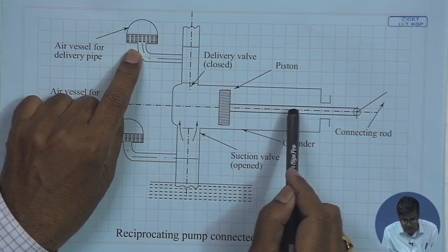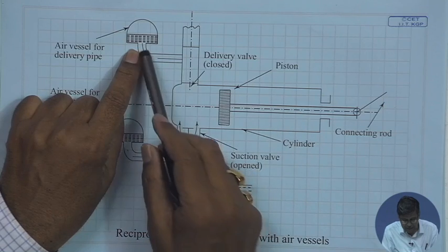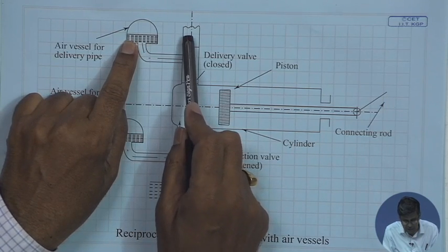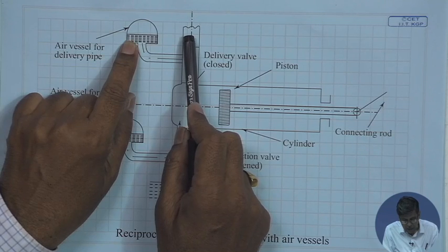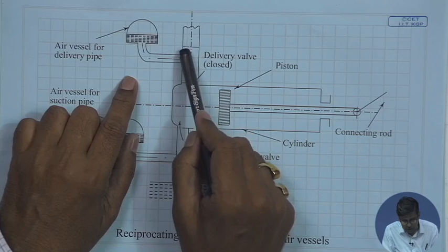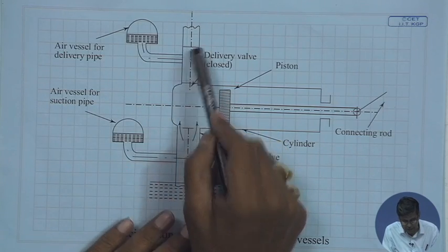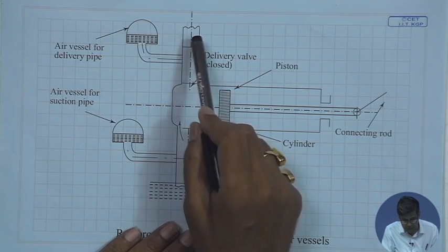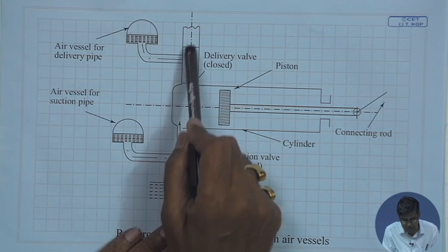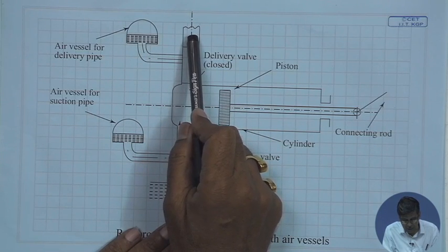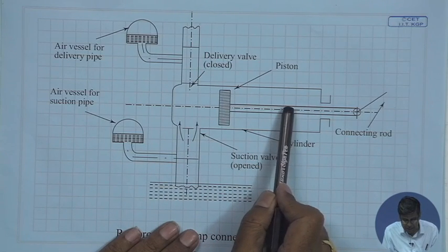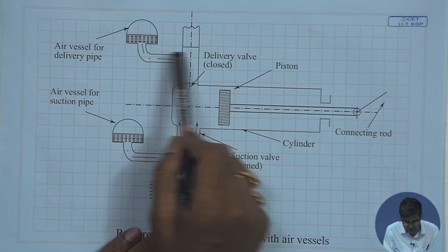When the initial acceleration is high and the discharge rate has to be more, this releases water and goes like this, and the similar thing happens at the end of the discharge period. So, therefore, the rest part of the delivery line, similar to the suction line, gets uniform discharge because of this air vessel. It gives additional water required in the initial part of the delivery stroke because of the acceleration rate, and similarly takes water to reduce it.